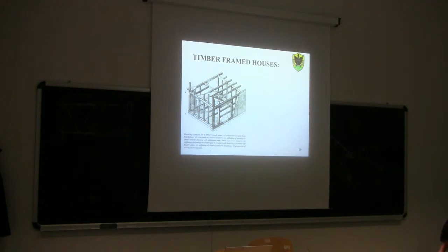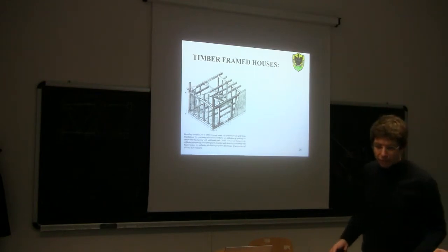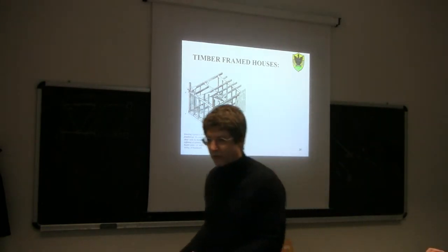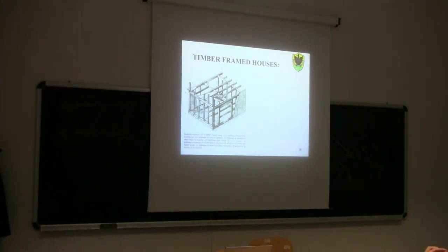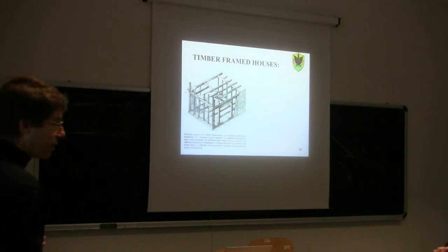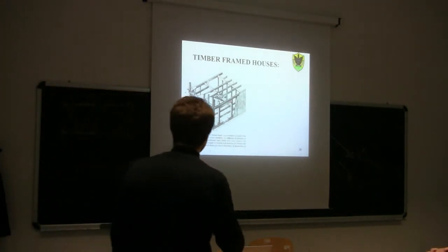I would say that in the Anglo-Saxon countries, the best material is plywood, which is used when you have more demanding application, and the worst material often used is particle board. However, in Italy it's not very common to find either one, plywood or particle board. So in Italy it's much more common to see the use of oriented strand board, OSB, as a cladding material.